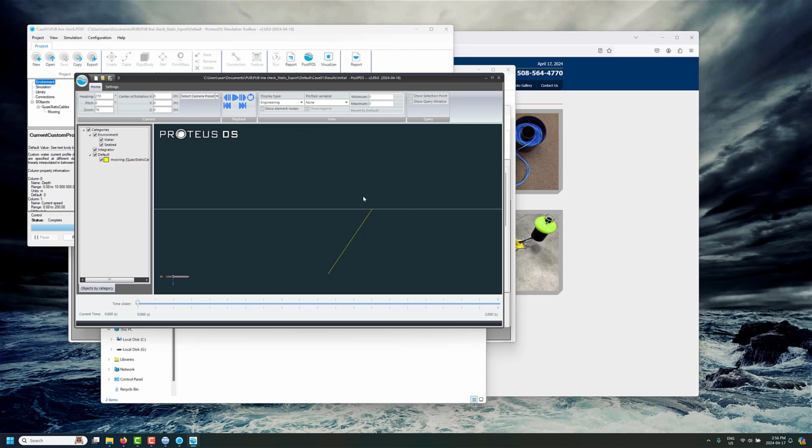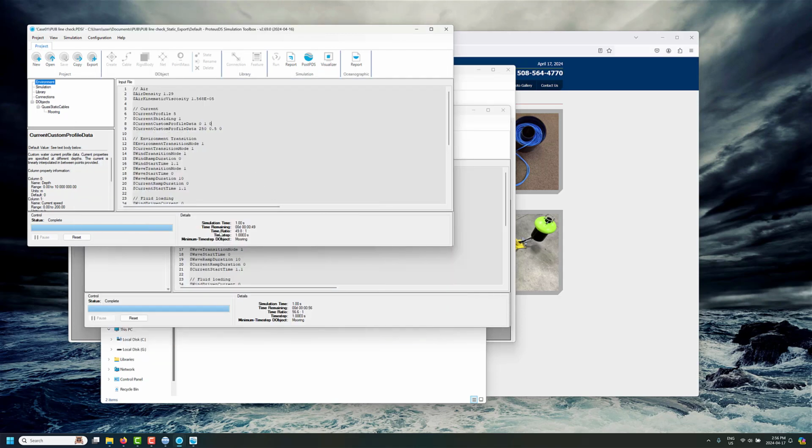So we got a nice side view here. This is the input format. It's just a diagonal line. This is the profile in zero current. You know, okay, we're all good. You've got the float at the surface here. But then in the current profile, it's well below the water surface. So in these kinds of conditions, you would not reliably be able to see the float or easily recover it. But that's a very high current at 2 knots.